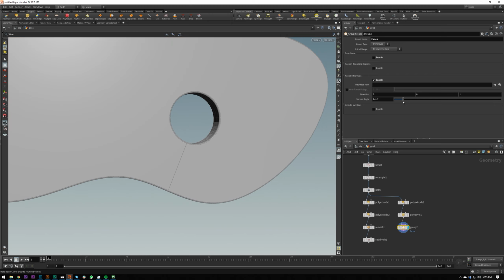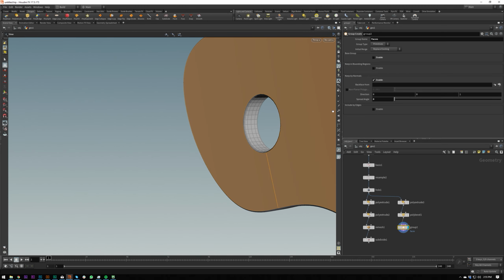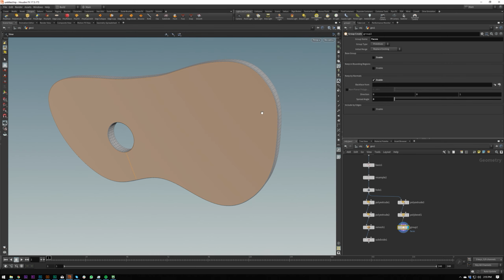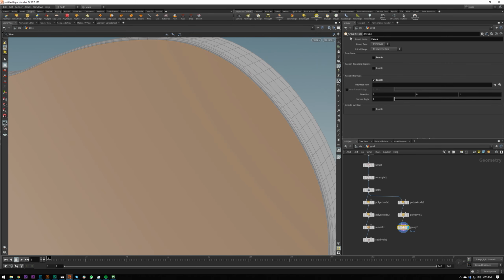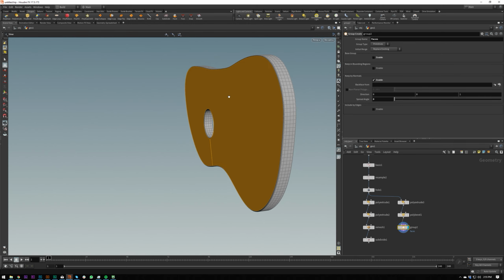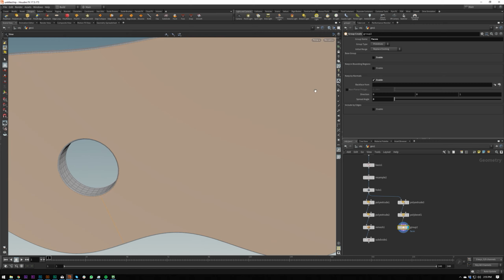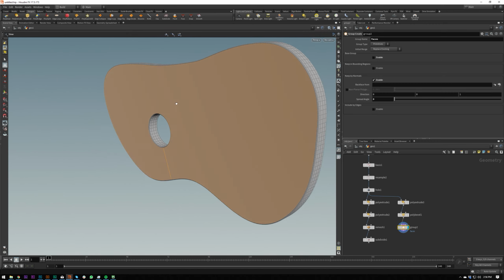And then if you turn the spread angle down to 0, you'll see that it's selected the backmost face. If we increase this, we'll get increasingly more selection, but we just want the absolute minimum selection here on this normal that is facing backwards on Y, or Z, sorry.